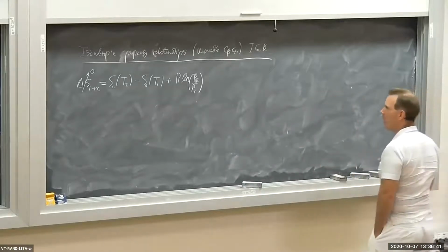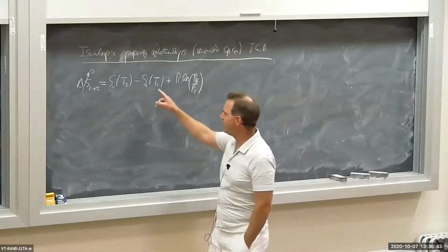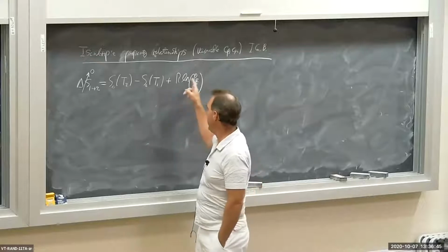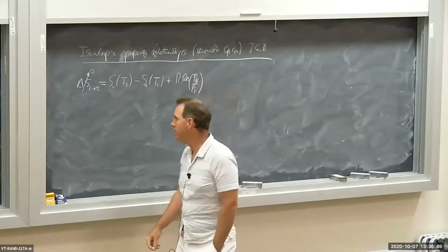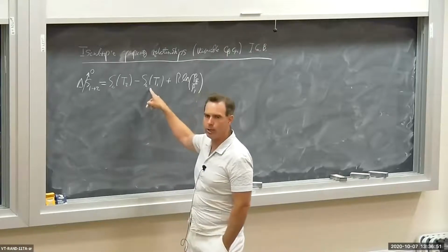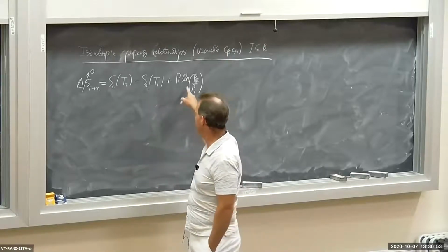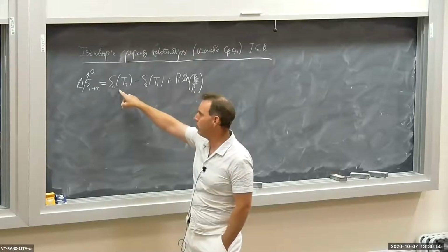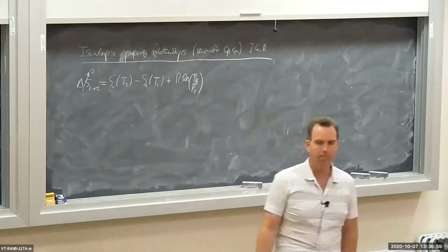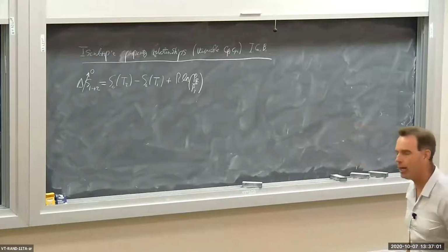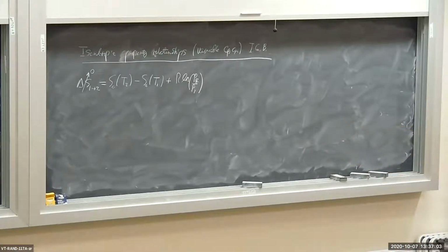So in theory, if you have, let's say, an initial temperature, and you have the two pressures, the initial and the final pressure, you can look up s naught at T1 in a table. You can calculate this quantity, and therefore you could calculate s naught at T2. And then you could back out the temperature using an IGB table to get T2. So you could use this equation.